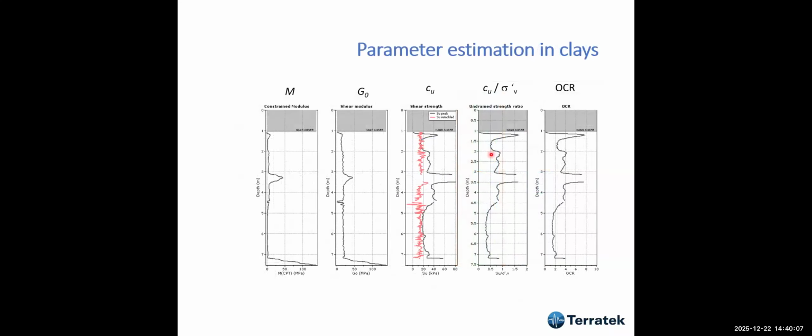It has been improved, and it has all these parameter estimations available, so you can estimate the constrained modulus, the shear modulus, the undrained strength, the undrained ratio, and I would say every 6 months or so there is a new development, something much better. So this software is very good.